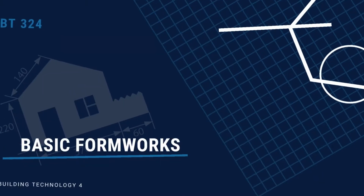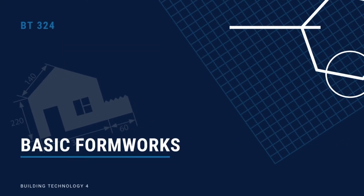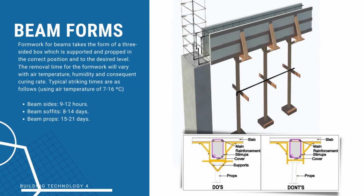Next slide. So the next topic is all about the basic formworks. Next slide. So first is the beam forms. Formworks for beams takes the form of three-sided box which is supported and propped in the correct position and to desired level. The removal time for formwork will vary with air temperature, humidity, and consequent curing rate. Typical striking times are as follows, using air temperature of 7 to 16 degrees Celsius. So the beam side must contain 9 to 12 hours. The beam soffit is 8 to 14 days. And the beam props is 15 to 21 days.